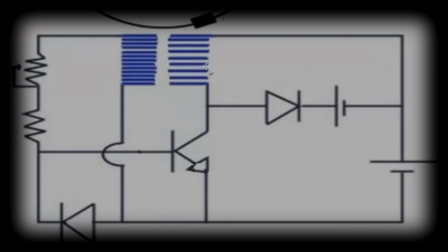During regular charging or forward charging of this drive coil, it will be getting a plus from here. So this will be the polarity put on the coil. And minus will be here once this switch closes and connects to the minus side of the battery, the source battery. That's your standard flow charge.